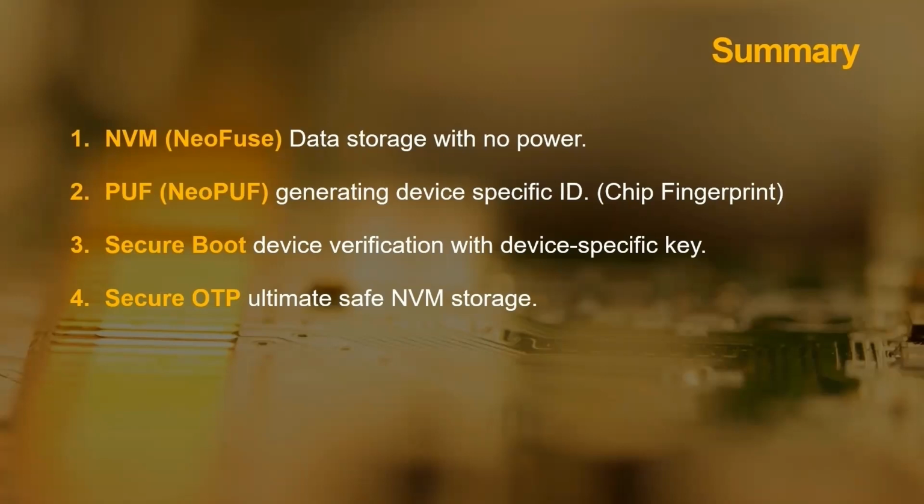Thus, we will need a PUF-embedded NVM solution to create a unique device ID and store key information with high data reliability. Secure OTP is a PUF-embedded NVM solution that can answer the need for secure boot in today's market. The Secure OTP offers a unique ID and reliable data storage and features random data scrambling that is unique between every device, while also featuring a list of protective functions that can further secure your data against hackers. And last but not least, the Secure OTP structure is a verified secure structure that can best protect your data.